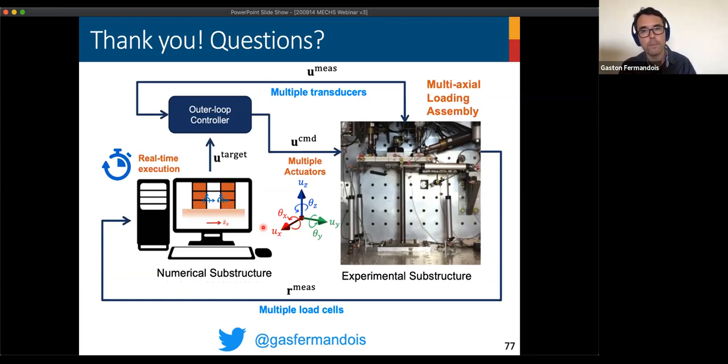So to get the best initial guess, we use this idea of first getting the best model possible in actuator coordinates, and then we obtain an initial model through a similarity transformation using the information that we get from the kinematics. But those kinematics are linearized kinematics. So this initial guess is only valid for that particular operation point.